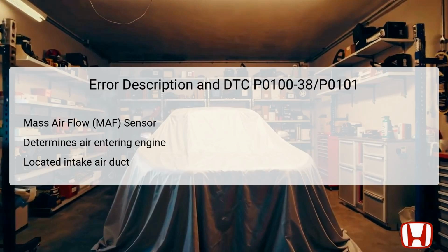The error description for DTC P0100-38 and P0101 centers around the mass airflow MAF sensor, a vital component within the intake air duct of the Honda CR-V. This sensor measures the volume and density of air entering the engine, supplying data that the powertrain control module PCM uses to optimize fuel injection and ignition timing. A correctly functioning MAF sensor is crucial for maintaining efficient engine performance and controlling emissions, making accurate measurements essential for the proper operation of the vehicle.